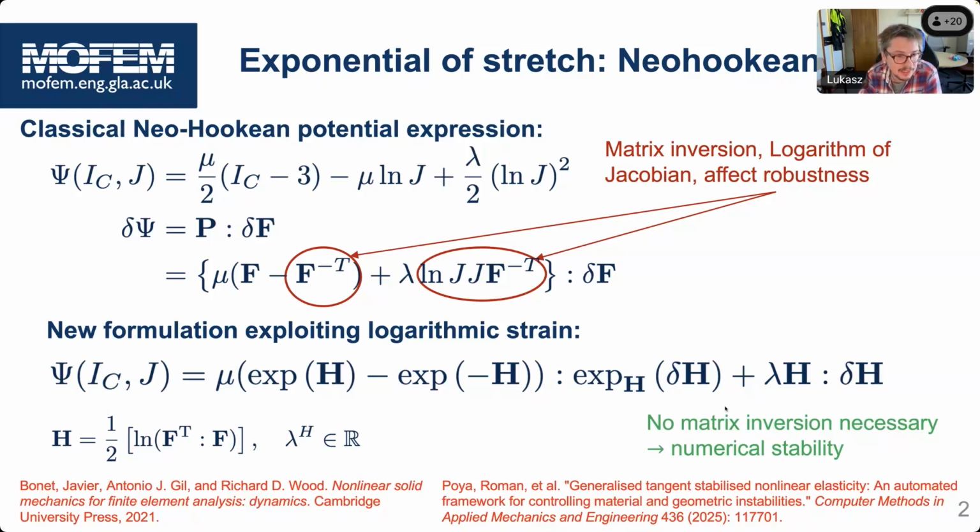So what about, instead of approximating the displacement, approximating directly the logarithm of the stretch, which is in our case h, so we can express a neo-Hookean material in the form you can see below, and then no matrix is inverted. When you approximate h on the mesh, for example in the L2 space, all the coefficients associated with the approximation are real numbers, not real positive numbers.